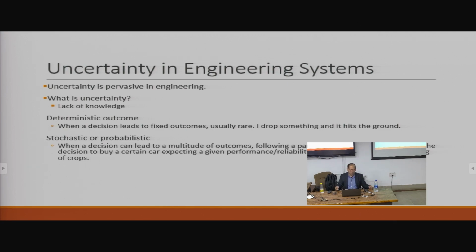These big processor companies are not making processors designed to withstand those clock frequencies. Essentially, they have the same process, but because of uncertainty, some cannot keep functioning beyond a certain frequency. So we'll bin them and sell them as a lower price alternative. And then some realizations, some chips will actually withstand higher clock frequencies, and then we can sell them at a higher premium, right? But it's the same design.